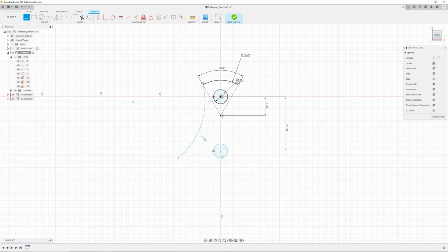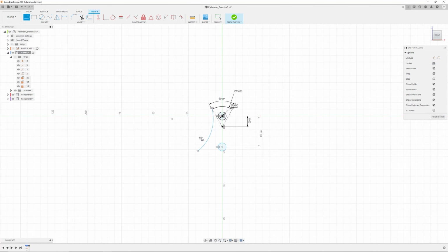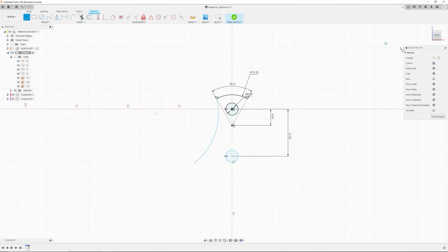And this one is going to have the same arc points as well. So I'm going to go ahead and do the construction. And I'm going to go ahead and draw those two like so. And this angle is supposed to be 70. And the radius of this, and you can see that number is much closer now, is supposed to be 35. Like that.